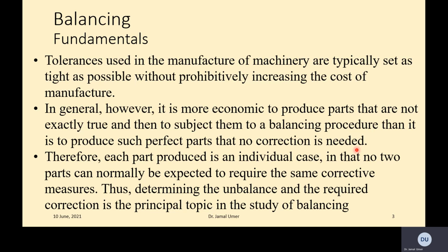If you want your part to be exactly of your dimensions, you make it at just 5. But mechanically it's very difficult because it involves a lot of machining processes, and that machining process also has some tolerances and some uncertainty, and the precision comes in. So you also need a very expensive machining process to ensure you are producing the part exactly of the dimension you need.